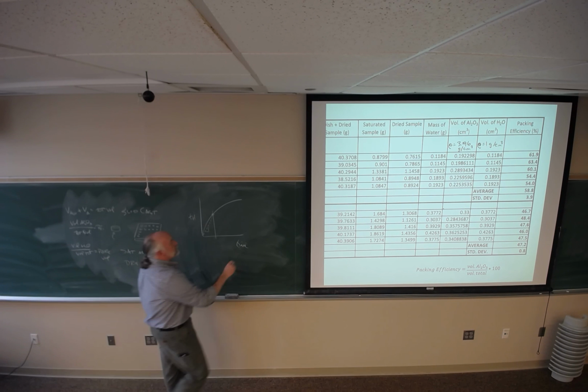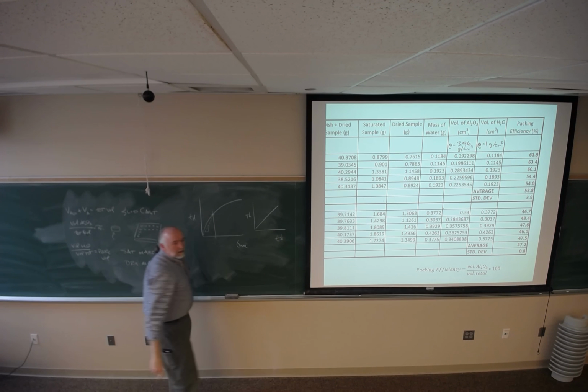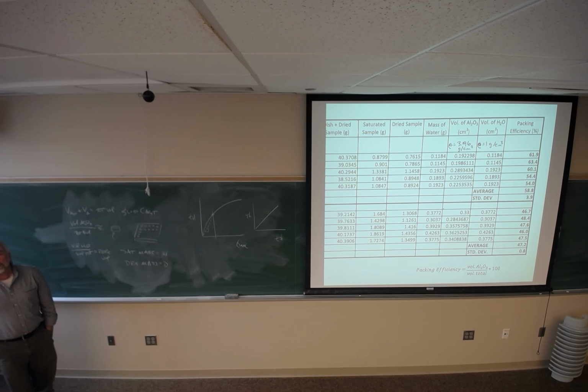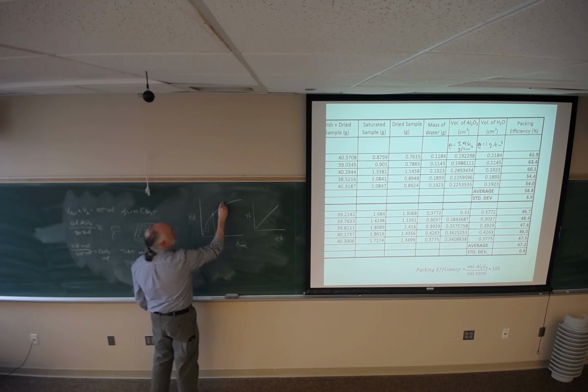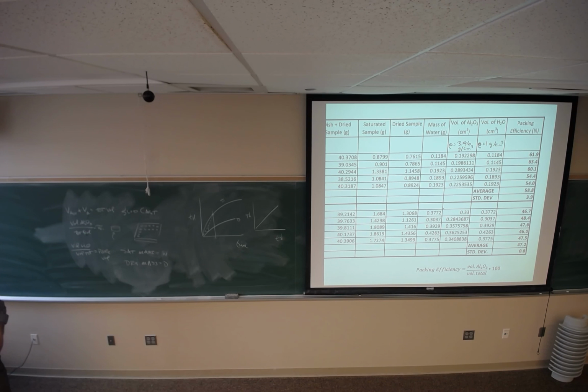If I plot this in a different manner, square root of time versus thickness, it's a straight line. What you find is, this might be for flocculated, this might be for dispersed, that the casting rates for dispersed are much, much slower than for flocculated, because the particles are packing more densely in the dispersed, with evidence of that in the density values, much more tightly packed. Therefore, water is going through a smaller pore size, so there's more hydraulic drag in the cast layer. That slows down the casting process, and so you get a much slower cast with dispersed.